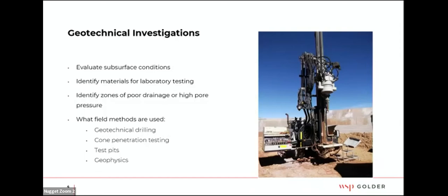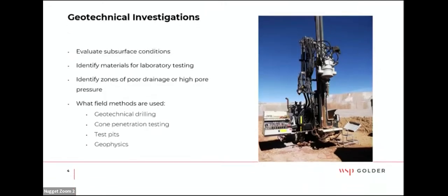Test pits for bulk samples at the surface. And then another great one, geophysics, which will let you look at resistivity over a very large distance across your heap. Drill holes are points in space, whereas geophysics can look at a much wider area and give you a better idea of the overall scope of conditions inside your heap.